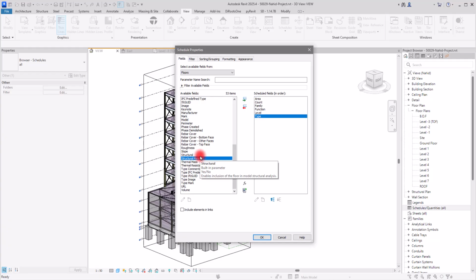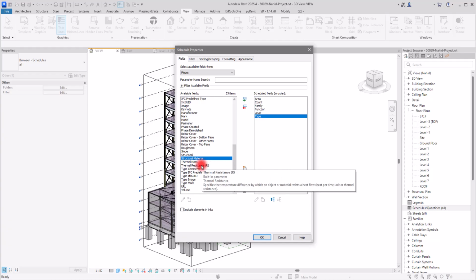We don't have the other materials because when you create the floor, when you create the wall, when you create anything with that structure section where you can layer different materials and their thickness, you absolutely need to have the structural material in the middle section. Okay, without this, you cannot create anything. So you can add this structural material even if it is like an architectural floor.